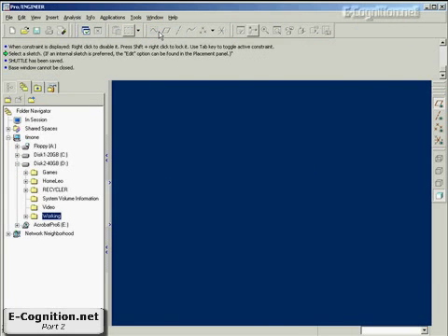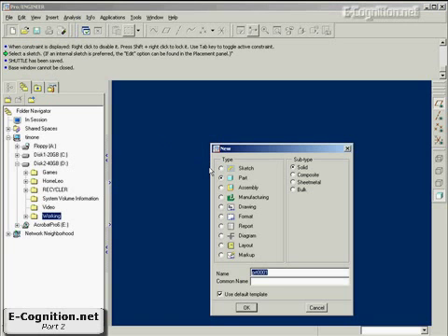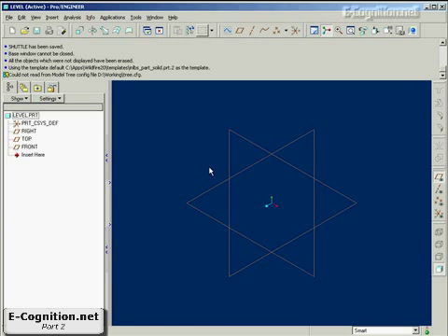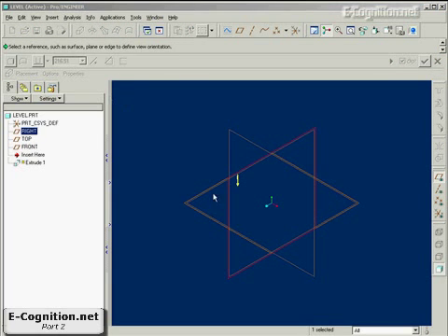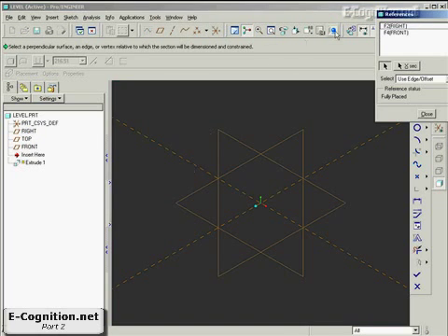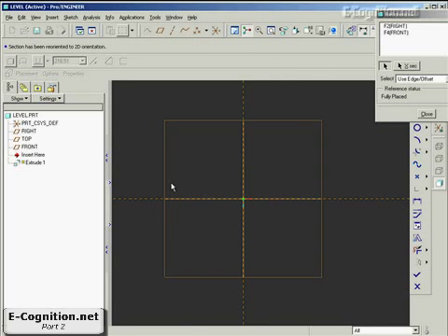and close the window. So the next thing we're going to need, we got a base, we got a shuttle. We'll be using 2 of those, and all we need is the lever. So let's make a new part. Lever. And this one's going to be a real straightforward part, just a plate with a couple of holes in it. So looking at it from the top plane, let's add a protrusion, go to the placement definition, middle mouse button. Let's look at it straight away.